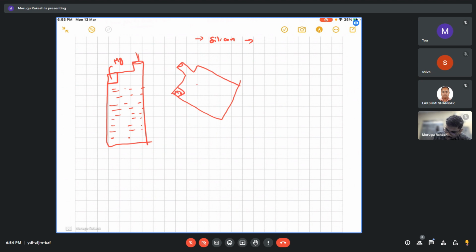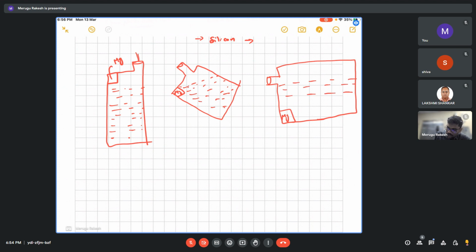So what happens is that this molten metal will come in contact with the magnesium slowly. Finally, we will completely tilt the mold. So this is known as the plunging method of adding magnesium to this ductile iron.